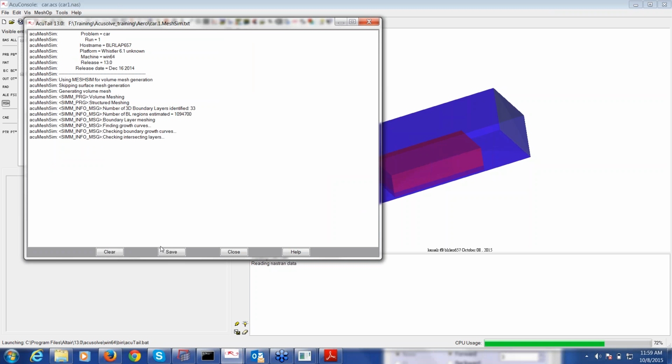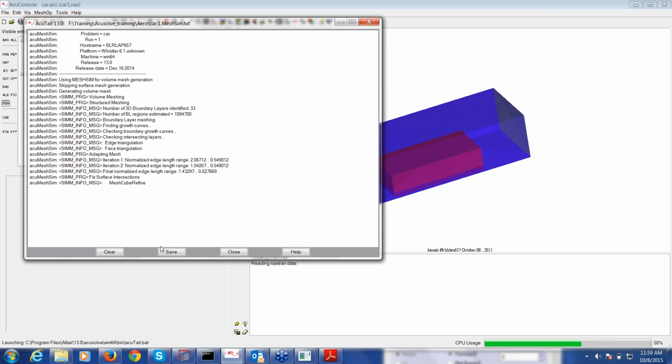You need to make sure that you give a very good global mesh attributes range, at least 2 mesh refinement zones over the wall of the car, minimum 5 to 10 boundary layers. So it is meshing.